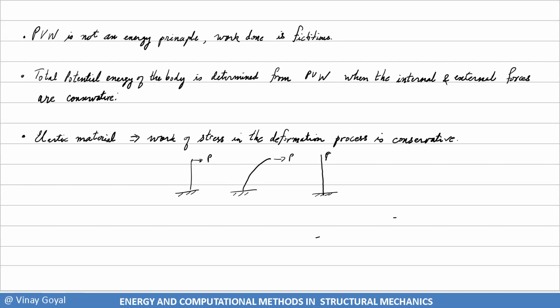Another point is what I mean by external forces being conservative. When I apply load P, that load does not depend on the deflections of the beam, meaning it stays directionally the same, so there's no change to that load.